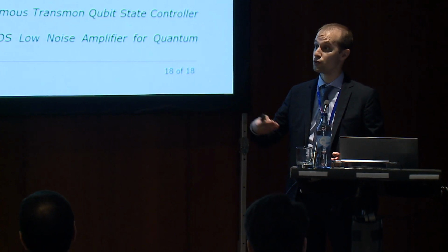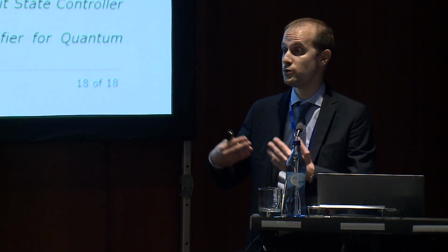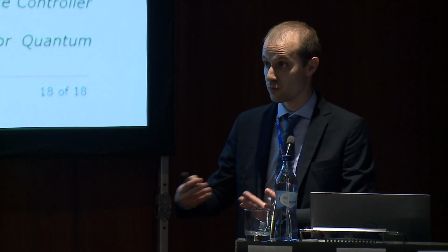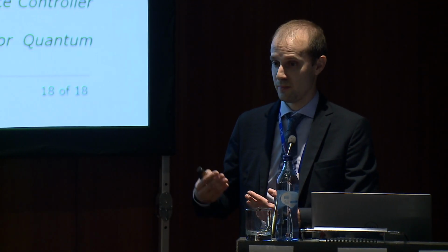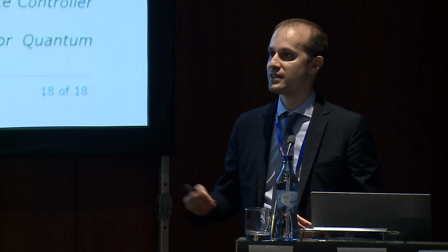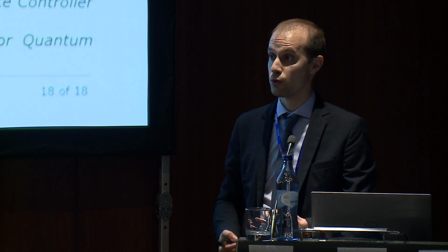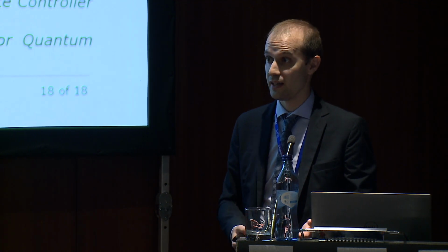For example, threshold voltage goes up, which means you have lower headroom, which means you need to go for topologies that do not place too stringent a constraint on voltage headroom. Or, for example, flicker noise typically gets worse at cryogenic temperature, so you need to apply techniques to mitigate that.